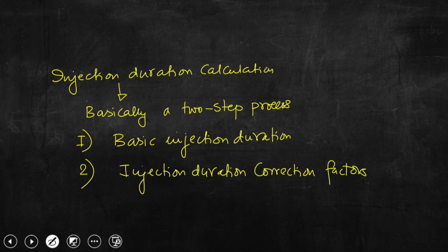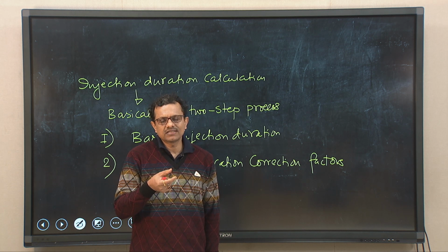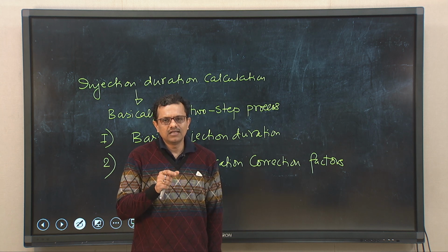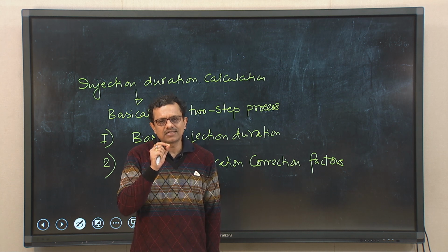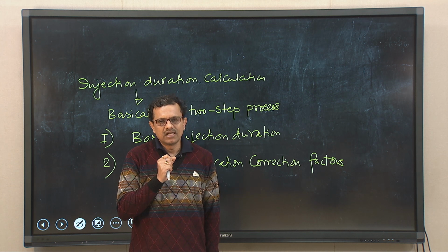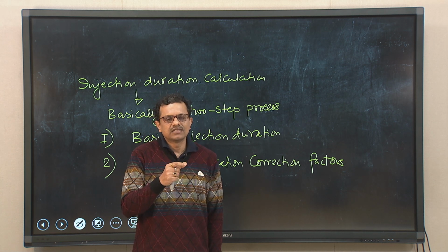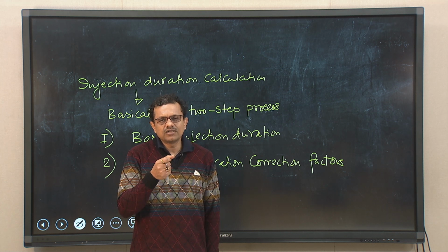So, you can understand we need to have proper or optimum injection duration. Essentially, the electronic fuel injection system is a part of the electronic control system, and the ECU will give some signal to the driver unit to operate injectors for the proper duration. And as I said, proper calculation of injection duration, that is the time duration of fuel injection, is very important to bring fuel economy as well as to reduce emission.